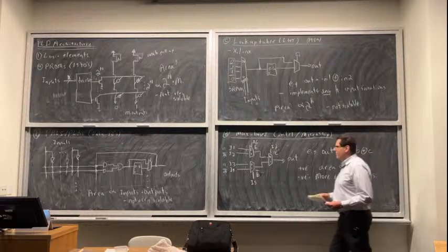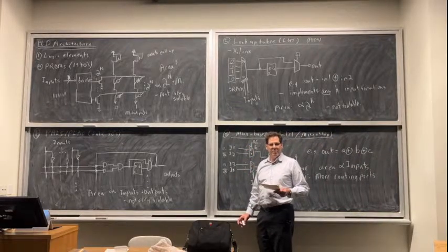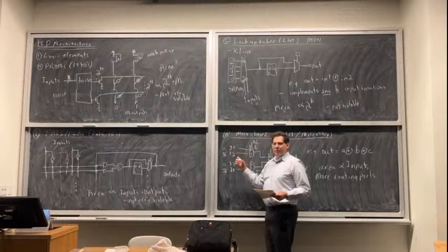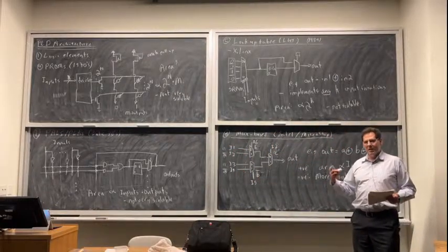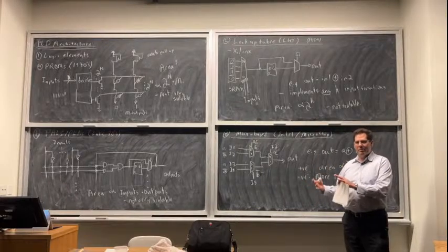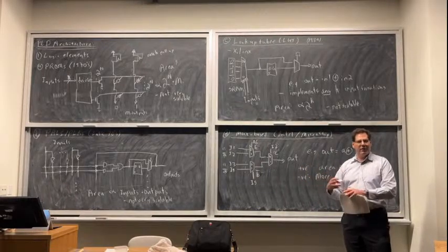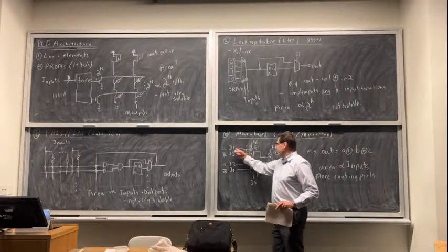Every one of these inputs isn't just a piece of wire, which even in an ASIC is a bit of a problem to have lots of inputs. To get an input here, we need programmable routing. And we're going to see in a little while what that means. It means prefabricated wires with inverters driving them, and more importantly, multiplexers and SRAM cells to control those multiplexers to switch between them. So these are pretty expensive.